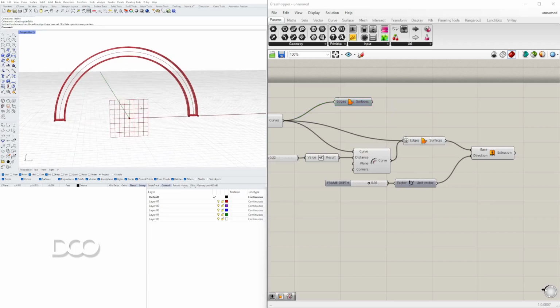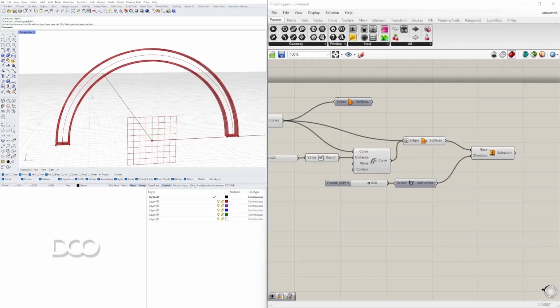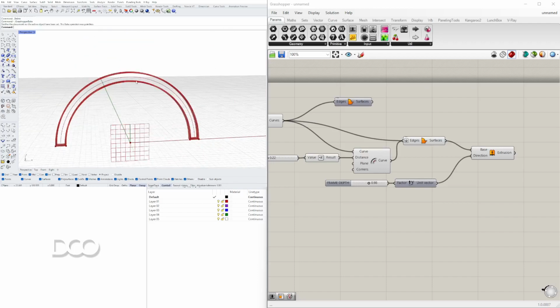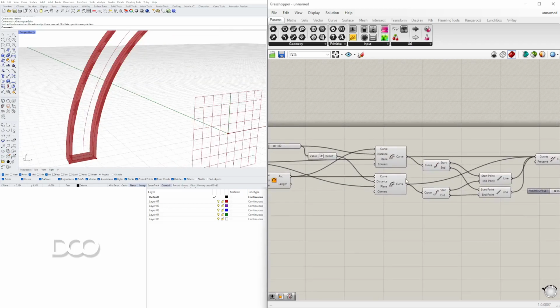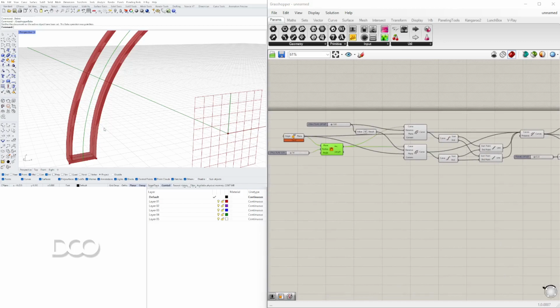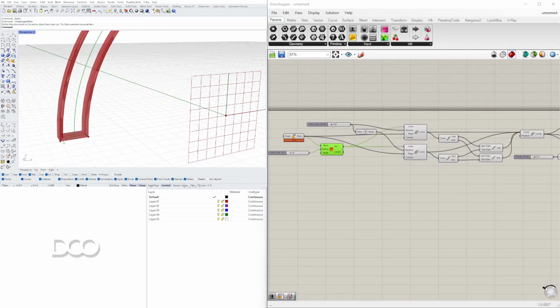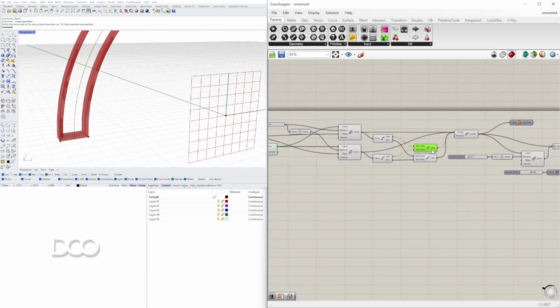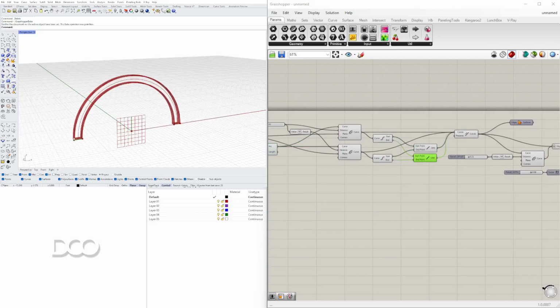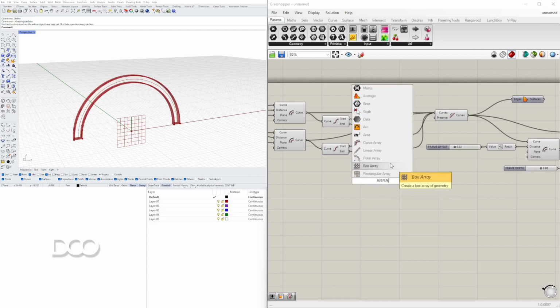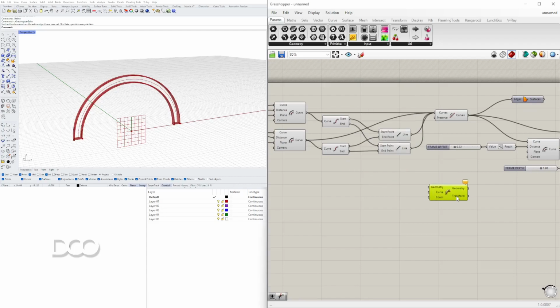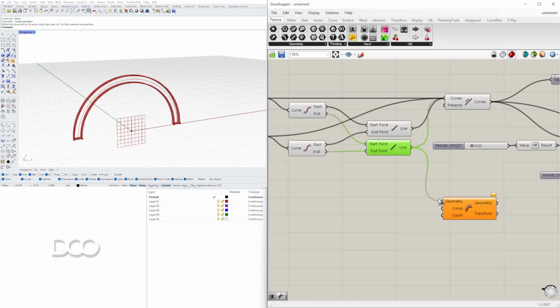And what we're going to do is create the segments that go in here using this original curve, so this arc, and we'll be creating one segment and arraying it around this and then moving it halfway. So let's start first by going back to the original arc, and let's also find this line segment that we have here, which was the one that closed the 2 offsets. So with this, we're then going to go to array curve or curve array, and we'll plug in the lines into the geometry,